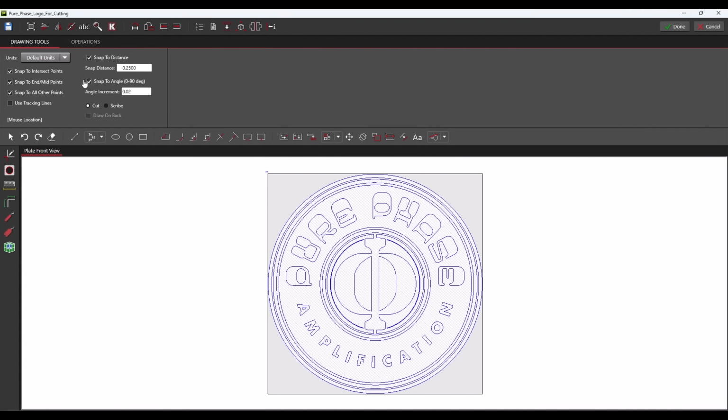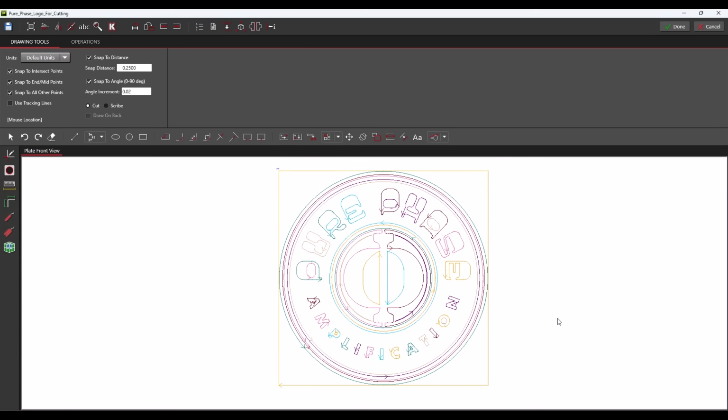Okay, so our CAD suite is loaded with our part, and now before we can edit anything, we'll need to explode all our operations into drawing elements. We can do this by coming over and clicking on this button with the several sticks of dynamite on it, or we can hit Ctrl-A on our keyboard. When we click it, we'll get a pop-up asking if we're sure we want to explode the drawing, and we'll click Yes. When we do, we should see the colors of our drawing elements change, and now we're able to select them for editing.